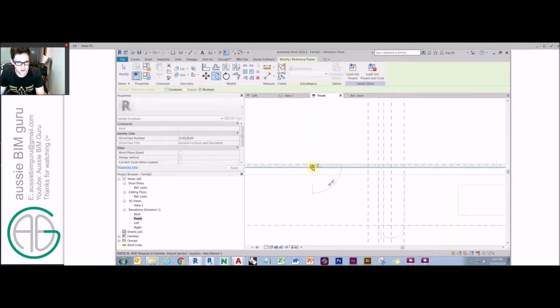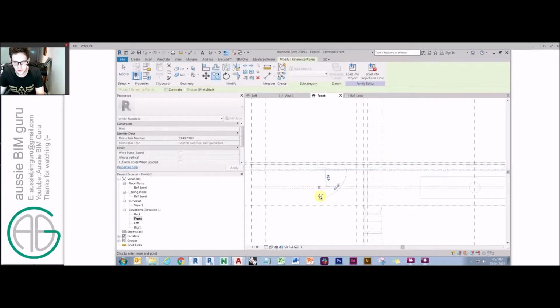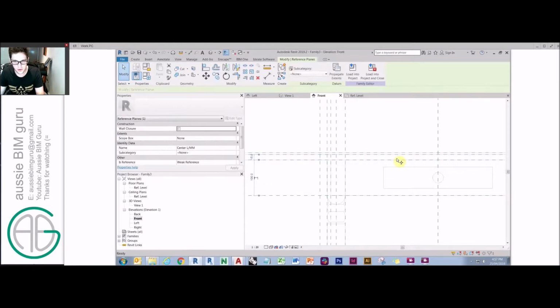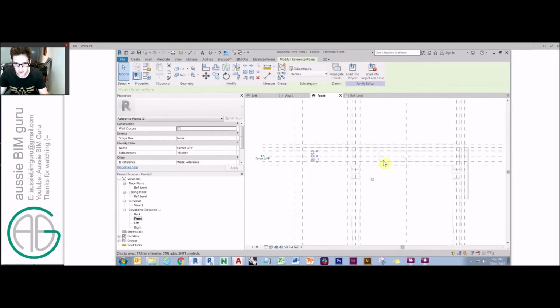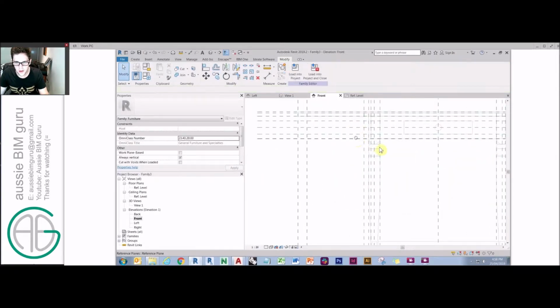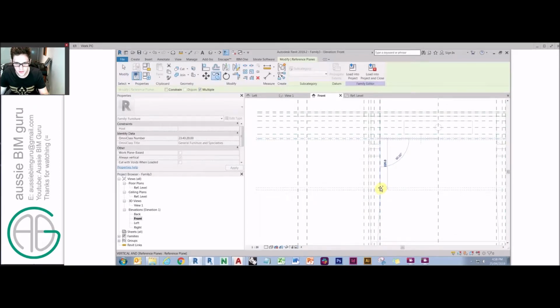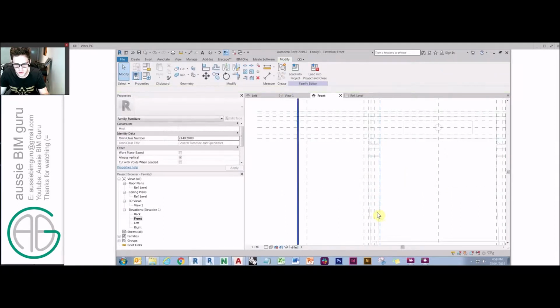So this is our top plane. We'll get the table thickness for the finish and we'll copy this down for the drawer. That is for the center line of the handle, which we'll need to constrain. From there, we need to copy down to a point where the table leg straightens out, because that will be the point where our family grows from. If you remember the last session that we did, you'll remember how that worked.